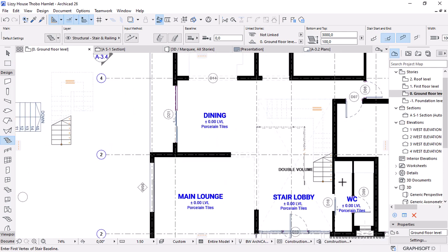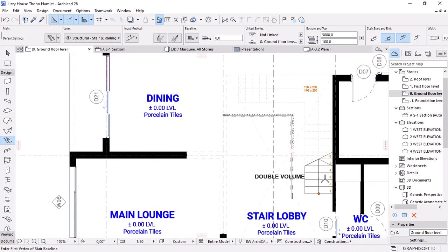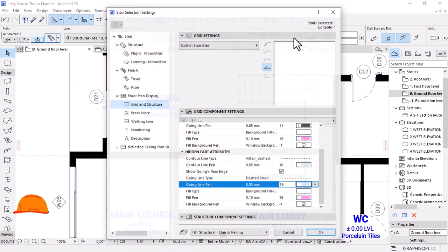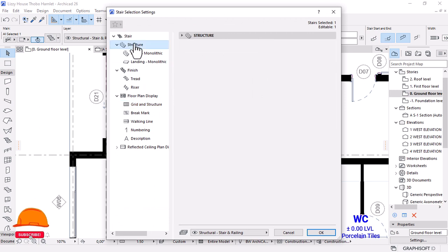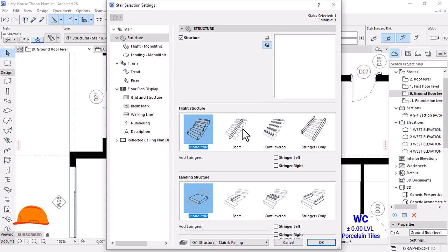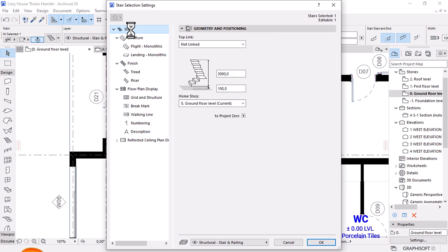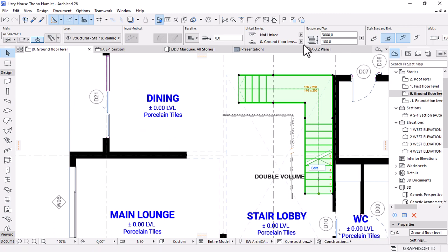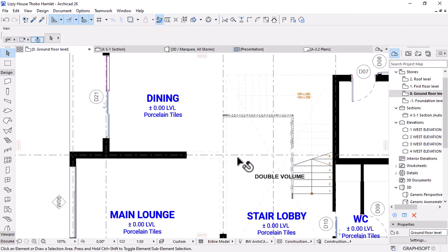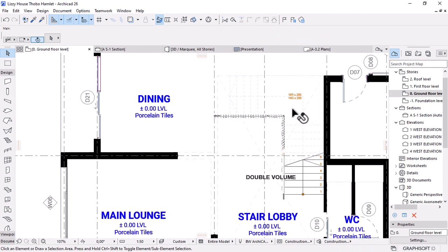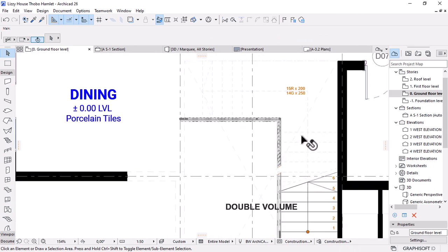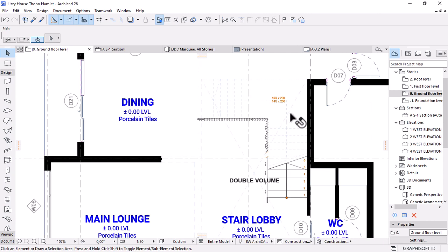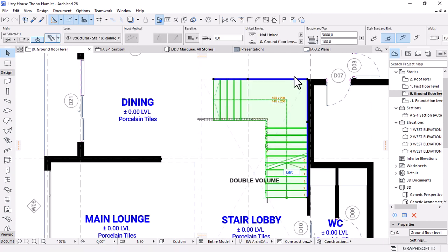There we go. But I think this one we need to adjust the stair width to 1.5. Should be under structure. Let's make it 1.5. Perfect. But I can break the line, I think, from the landing instead of before the landing.